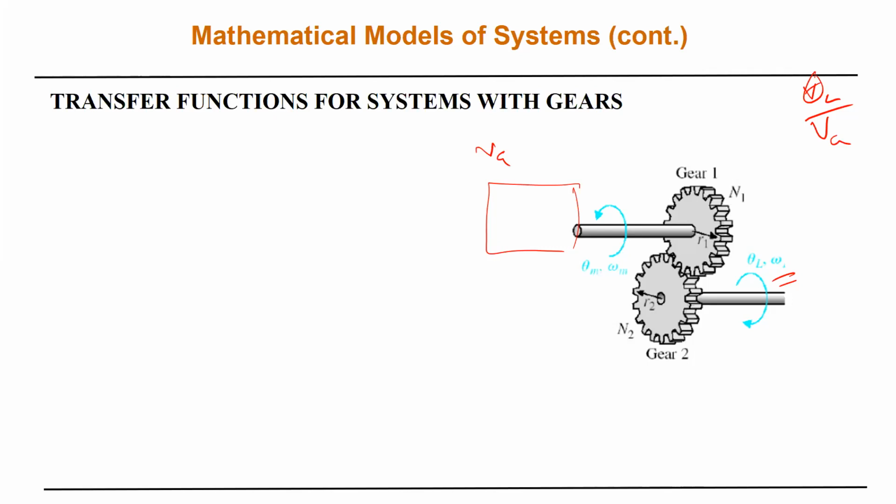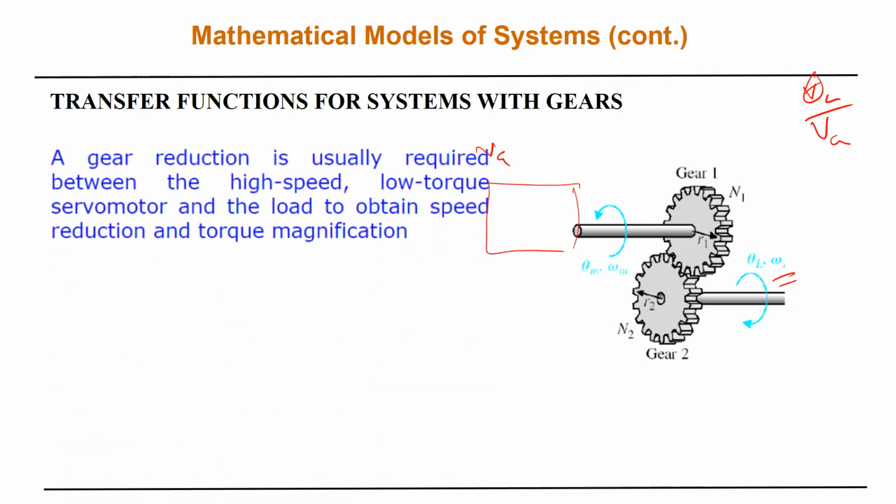Usually in the motors we have high speed, low torque, and in the load most of the time what you need is high torque, low speed. So we will use the gears to adjust these things, to adjust the speed and to adjust the torque.